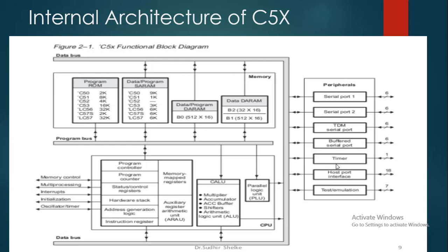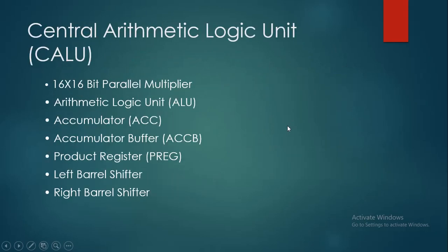And there are some maskable and non-maskable interrupts, like INT1 to INT4 for external maskable user interrupts, and not only that, NMI, INTR, TRAP, RST; these are the different types of maskable and non-maskable interrupts.